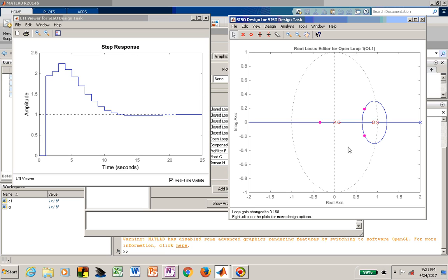if we wanted to leave it at that. And you can see then that I can change this by adjusting poles and zeros. I sort of like that zero at 0.1 and the other one at 0.9 and adjusting the gain to get me around to 0.7.